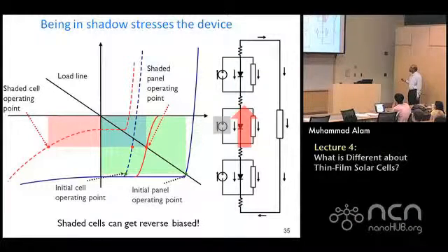If it loses power, then it must go down. It doesn't have any photogeneration anymore. It must go down and get in the reverse bias, break down, and supply the current that the circuit dictates that it must have. And therefore, the remaining two must now give up a little bit of voltage to help it break down even more so that it can give some current in the reverse bias. And your total output will be dramatically reduced.